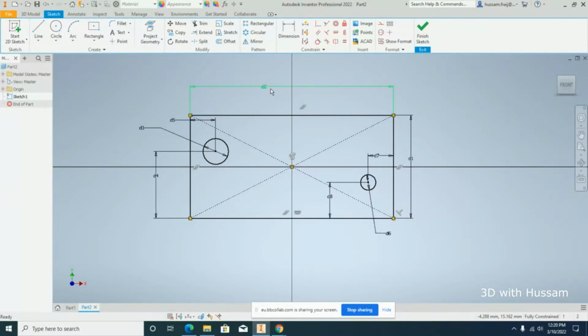What do I mean by dimensions that I know and I can benefit from? Like this, I will show you. Before I double click on 40, down here when you click on value and name, the third one is called expression, which is name and value at the same time. So the first one is only value, the second one is only name, the third one is name and value.